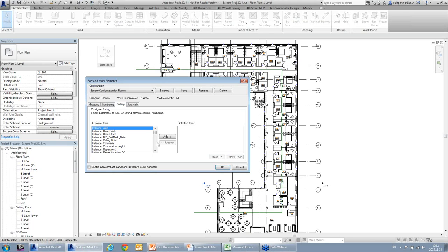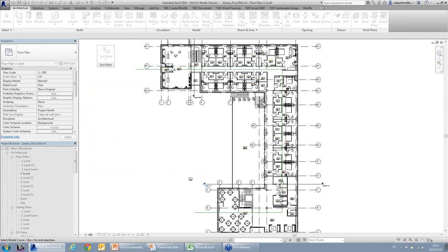And in the sorting tab, I will pick one additional our created parameter that allows you to sort your elements according to the model lines. Here you can add your own tolerance, and now after pressing OK, the tool will let you pick the lines from the project. So right now I will pick those 3 lines.